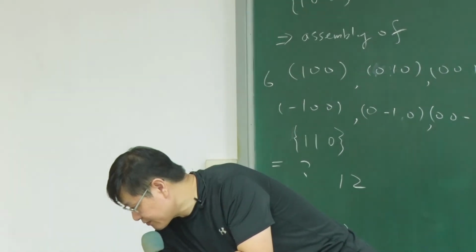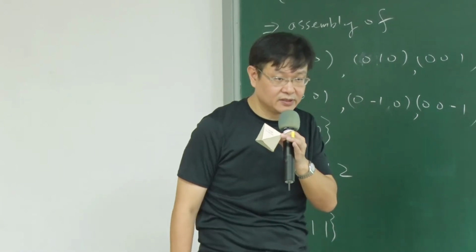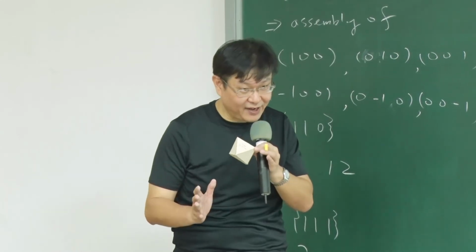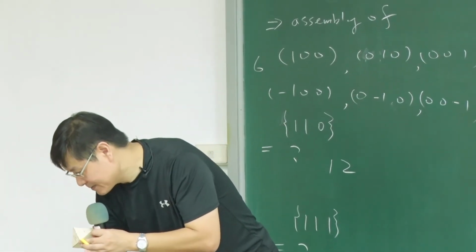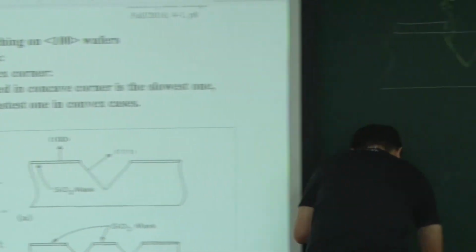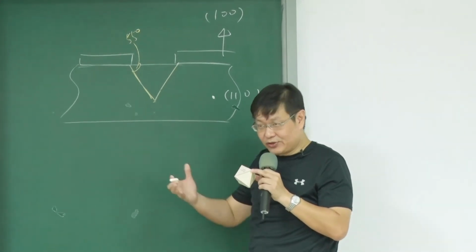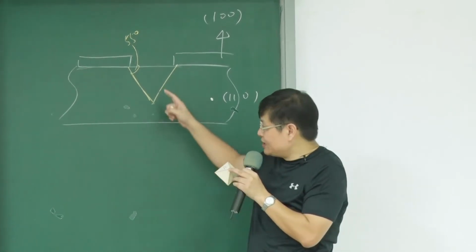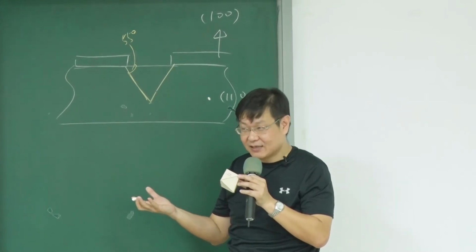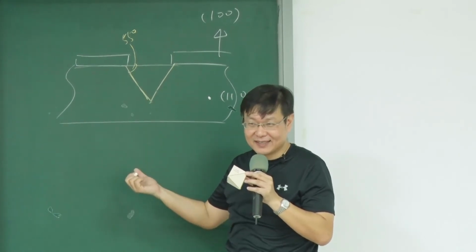So we are talking about this surface and this surface. The angle here is 55 degrees. Remember, it's not 45, it's not 60. It's 55, okay? Let's come back here, okay? Because this shape is your final shape. So during the etching progress, your intermediate shapes will not be over the final shape, right? It's logical. You cannot take more material than your final boundary, okay?